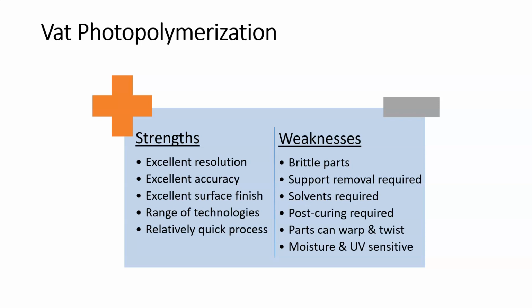And those are printed using the CLIP process, vat photopolymerization, CLIP technology by Carbon, and others at this point. And that really tells you right there that those shoes could not be made from brittle material if they were going to last for any length of time. So the brittleness here depends a lot on the material and maybe to a lesser extent the technologies.